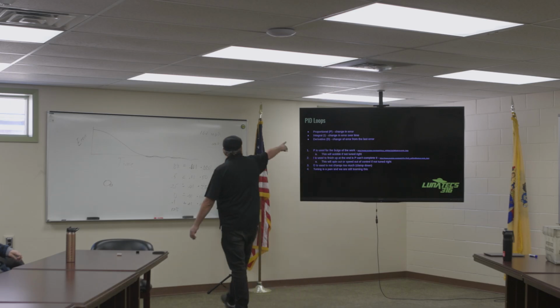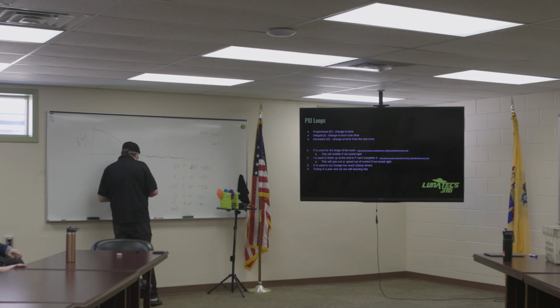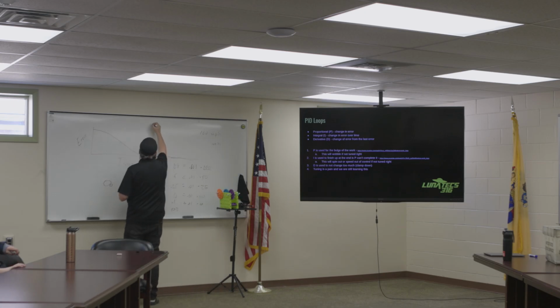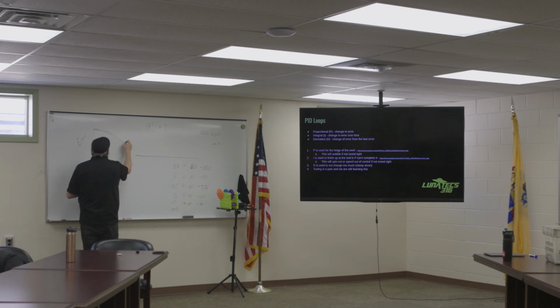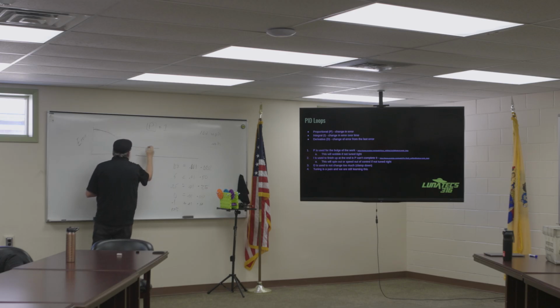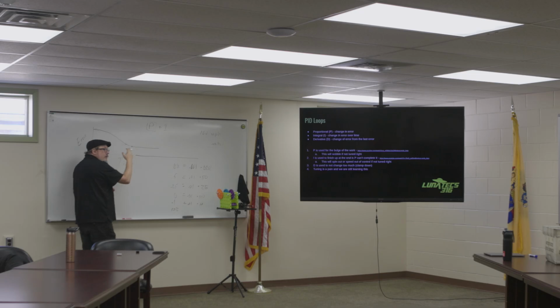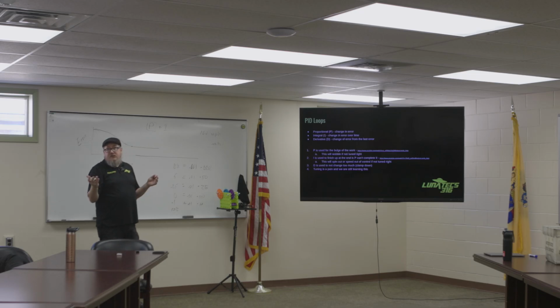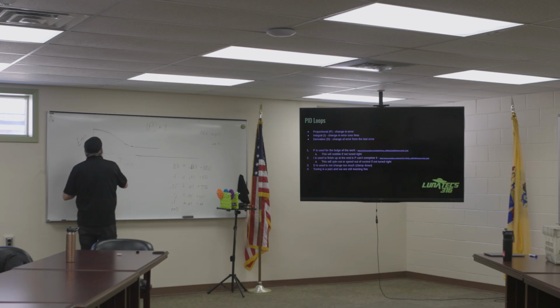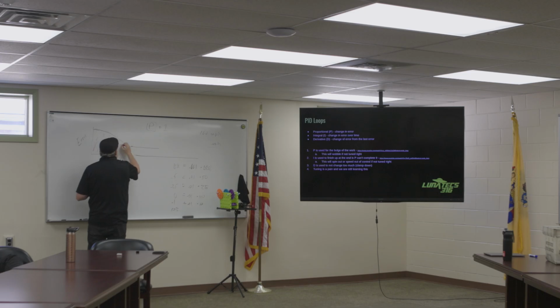So we can use what is known as integral, and that is our second component. Proportional gives us our initial power, and we can add integral to that. What integral is: over time, let's say something stops me from getting to my target, a block. I can take the area under this curve, right?